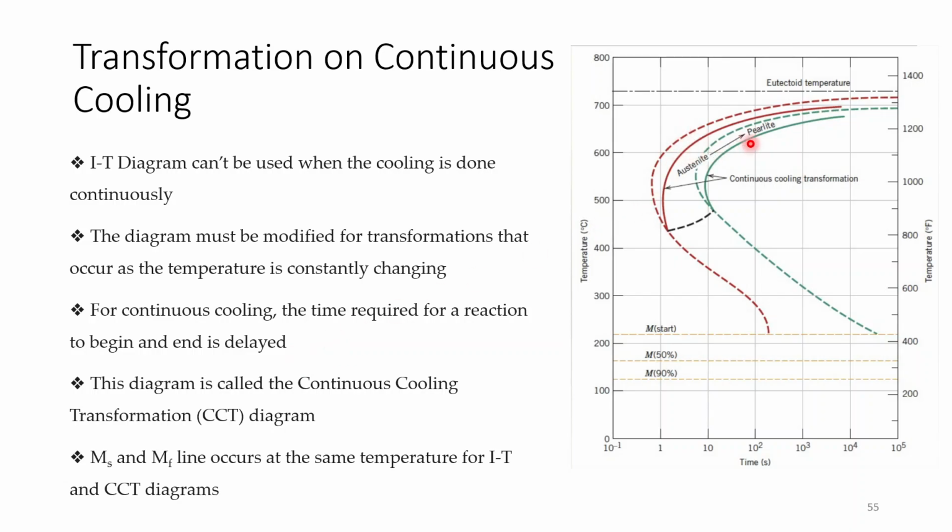Okay, so why? Here, in the solid line you can see continuous cooling curves, and with the dashed line you can see the TTT diagram. So in this case, if you are cooling with continuous cooling, then you will encounter this solid line, the continuous cooling transformation curve.